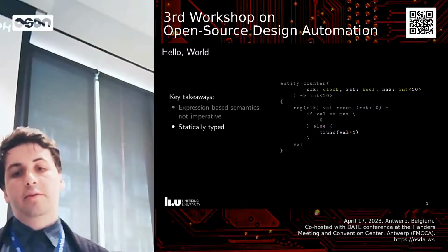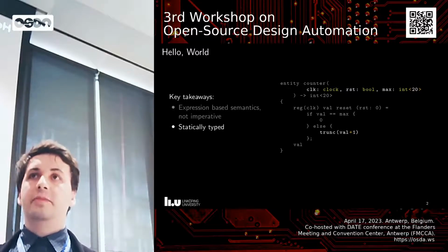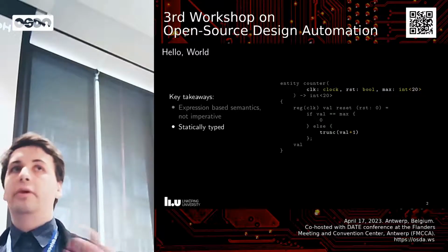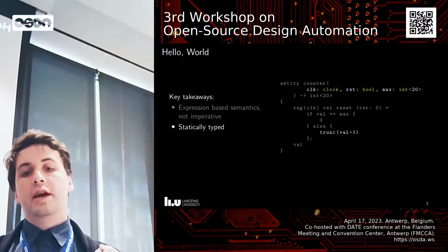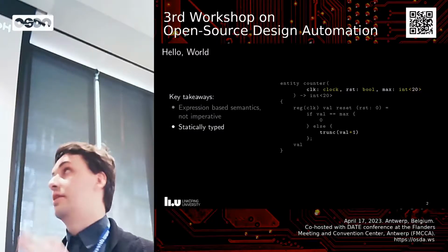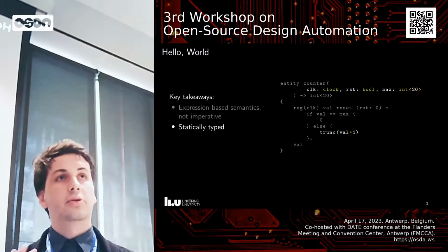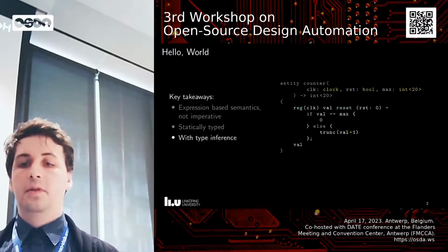It's a statically typed language, so we specify all the types. It also tries to make sure that you don't accidentally throw away information that you might need. So if you do val plus 1, that could overflow, so the language will not allow you to throw away that overflow implicitly. You have to call this trunk function to say that, no, I actually do want to throw away a bit here, since we have a feedback in the circuit.